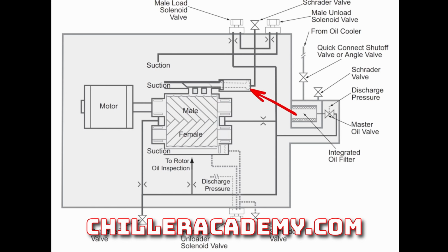So once the compressor gets turned on and has a minimum run time of a couple of minutes, it's going to register that the refrigerant circuit is stabilized just based off a time delay. There's nothing fancy going on there. And then it's going to see that, hey, we're still not meeting our leaving water set point. So at that time, this particular one uses oil. As part of the oil circuit, it's going to use that oil and these loading valves to physically push the slide back and forth.